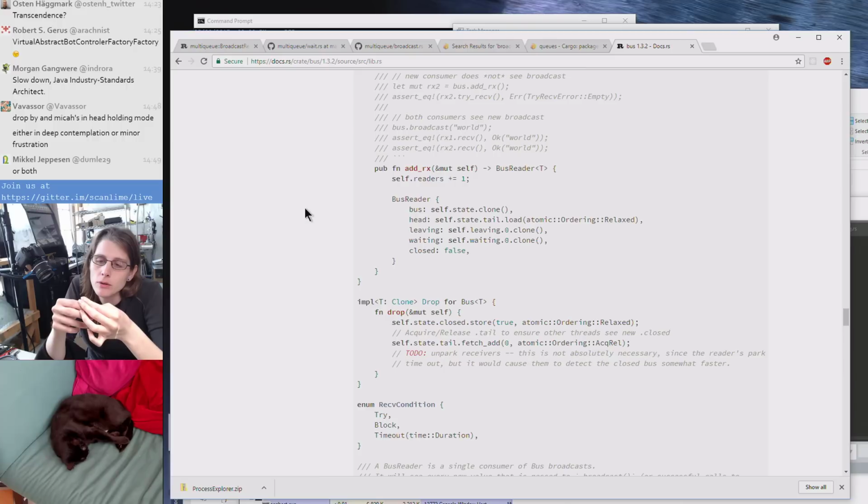And how would that work? So some input comes in from the robot. There's the bot com thread, which is waiting on UDP. And it gets the message, sends it along to this multi-producer, single consumer channel. Other input sources like the gamepad do the same thing. They get combined in the channel. All of those get funneled into the controller, which processes some of them. Relays all the messages to the output queue. So you can listen to the output queue and see the same messages that were coming in from the input, but then it also adds its own messages. I kind of like that.